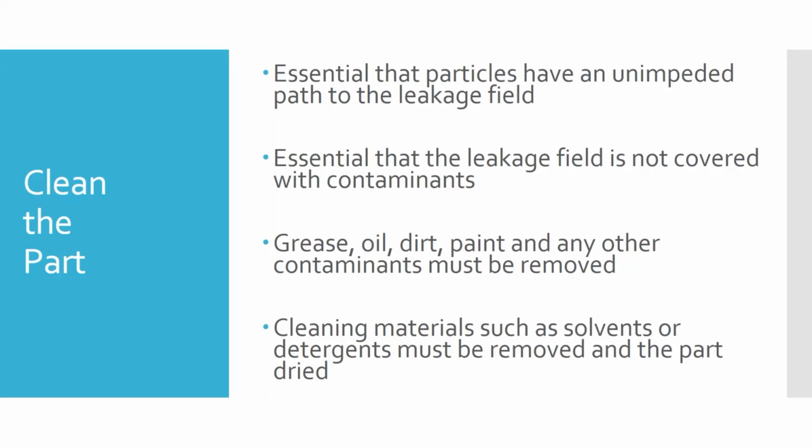So it doesn't rust, could be part of it. It doesn't burst into flame. We're not servicing oxygen here. So what if I have a part covered in alcohol and then I go put it in the mag particle bench that's full of an oil-based carrier? You think those will react with each other? Alcohol breaks down oil, by the way. So it's not going to react properly. Okay. So we want to make sure they're clean, they're dry. So don't let your cleaning materials become contaminants in their own right.